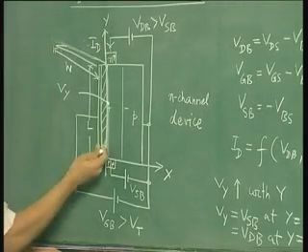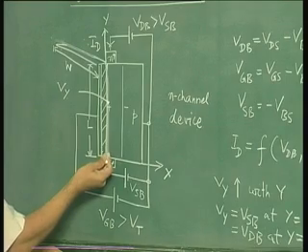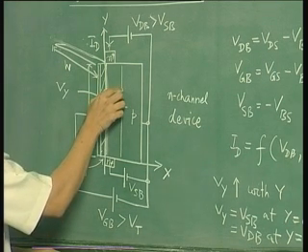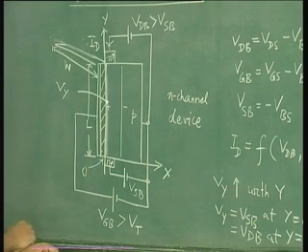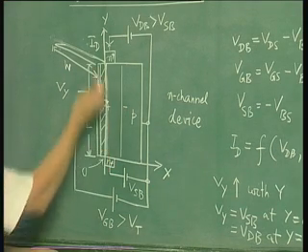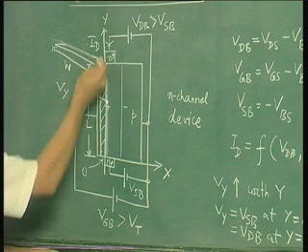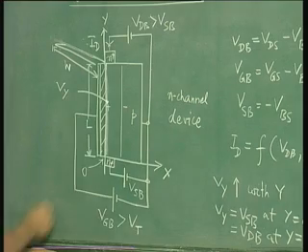So in other words, this is a MOS capacitor with a changing body effect from source to drain. So the body effect is increasing from source to drain. So total charge should reduce, but depletion layer charge should increase. So inversion charge should definitely reduce as you go from source to drain. So as your body effect increases from source to drain because of increase in Vy, the inversion charge will reduce and depletion charge will increase.